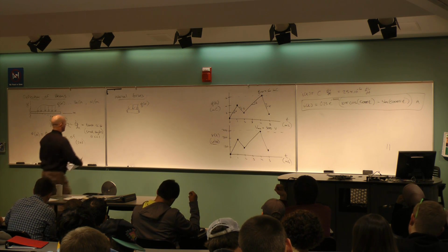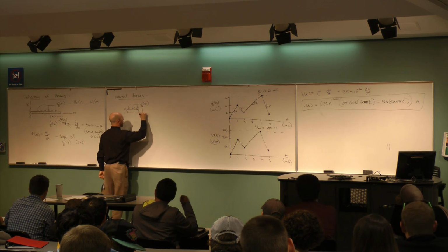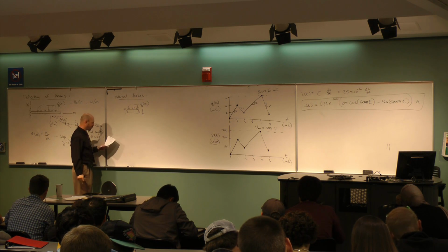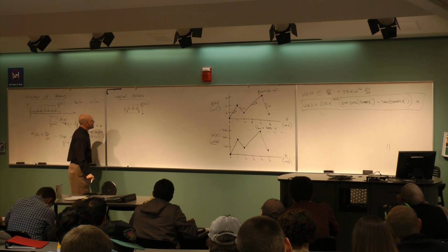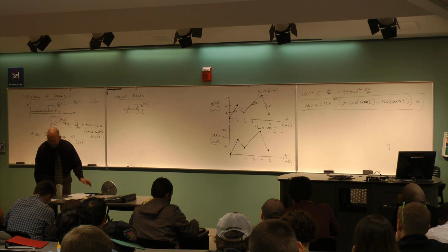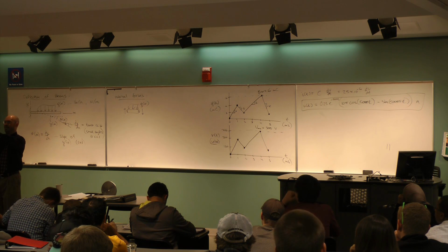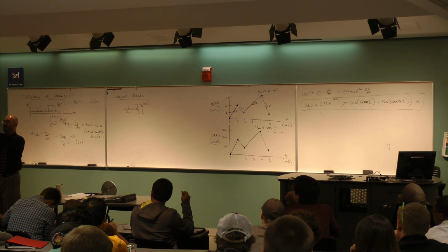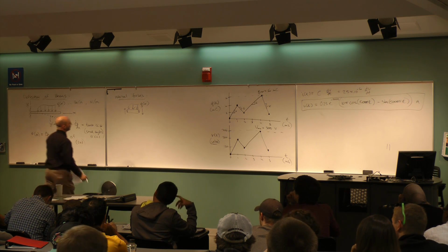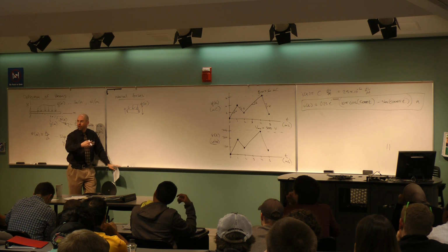So I can take a section like this, and I could say, well, what would I have in here? I could have a combination of forces up and down, transverse to the beam. Those are called shear forces. And then the other thing I could have, if this beam is going to be bent into a shape like this, is what's called bending moments in the beam, which is the idea of force multiplied by distance. In high school physics, they call these torques.